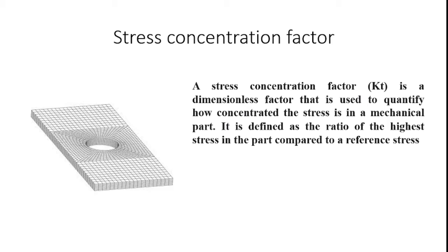It is defined as the ratio of the highest stress in the part compared to a reference stress, which is called the stress concentration factor, because most parts and fatigue specimens contain points of stress concentration, such as surface roughness or changes in part or specimen section, so we should be aware of what the stress concentration factor is.